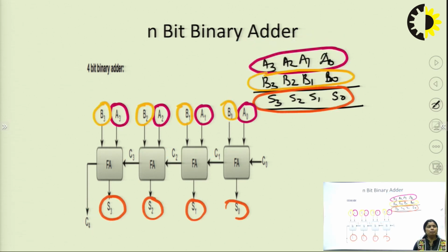So, in the n-bit binary adder, simply we are taking A0, A1, A2 with the addition, because the addition is there, that's why we are taking a full adder. At this time, the carry value C0 equals 0, because when the LSB is taking A0, B0, the carry will not be generated. So that's why at the initial time, C0 is 0.